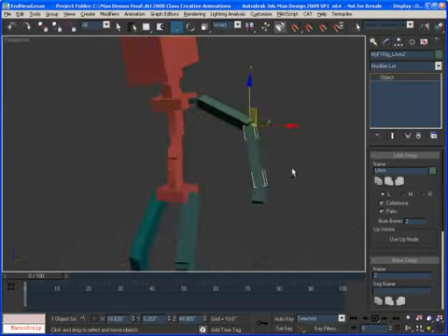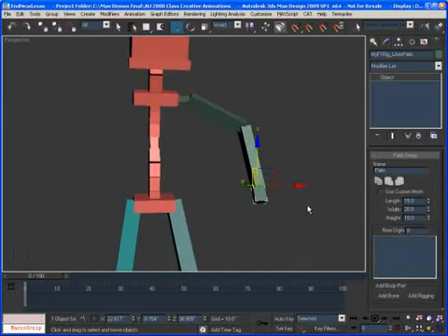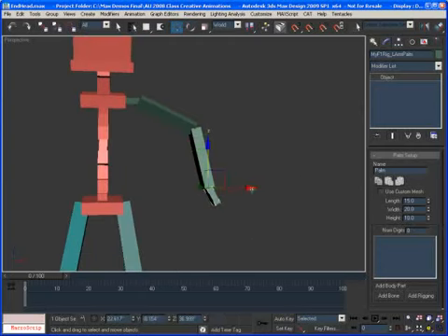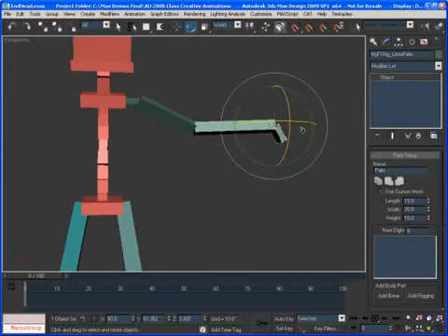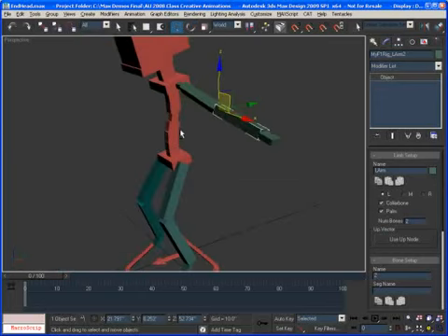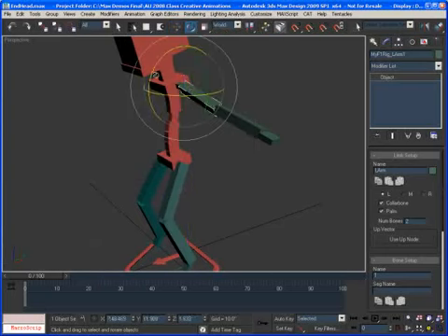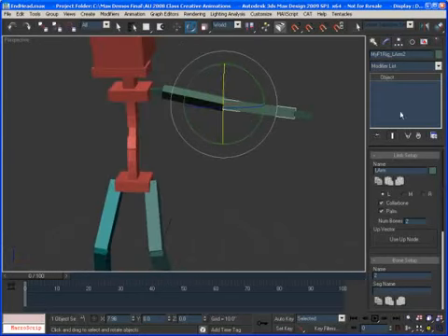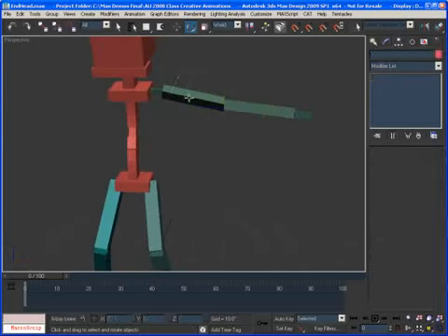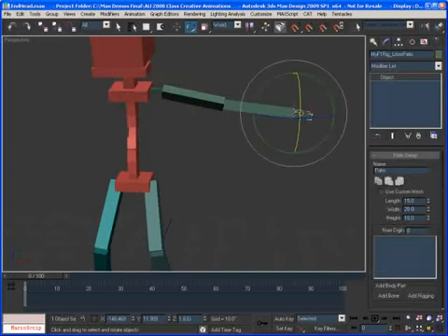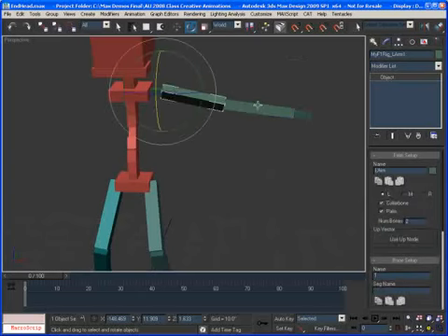If you want to do a T-stand pose, I'm going to grab the hand here, rotate it like so, and bring it up like that. Maybe rotate it like that, and bring the shoulder like so. So rotate this one here a bit. Here we go. If I want to create some twisty bones, again, same idea. It's the same exact thing as the leg. It's just that the difference between a leg and an arm is that the IK chains start after the clavicle and end at the palm here. So instead of being an ankle, it's a palm, but the logic is exactly the same.